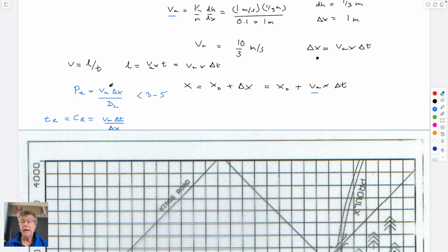You don't yet have, you don't either have a control on the dispersion coefficient, because this is a function, for mechanical dispersion, of the flow velocity and the length of the plume divided by 10. So the only parameter that you can control is this. So to get a Peclet number that satisfies this, you have to make a mesh that instead of looking like